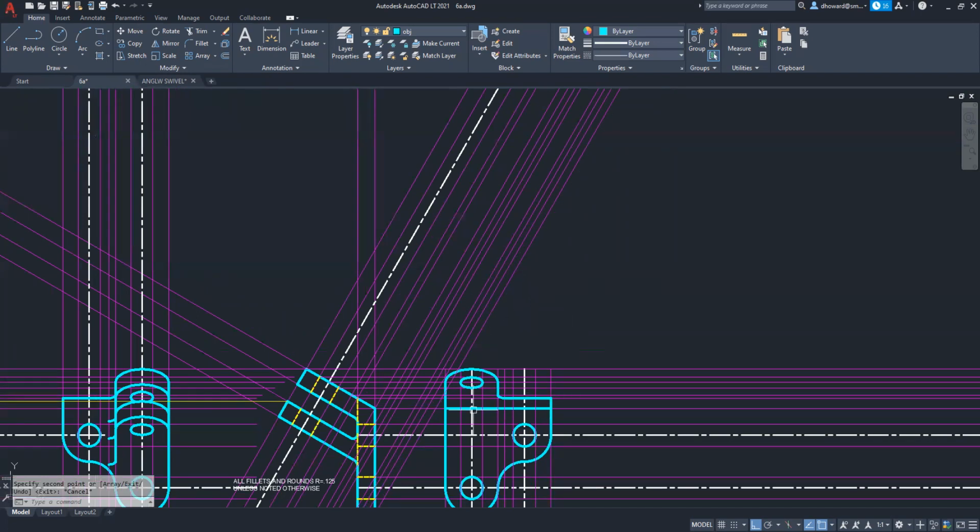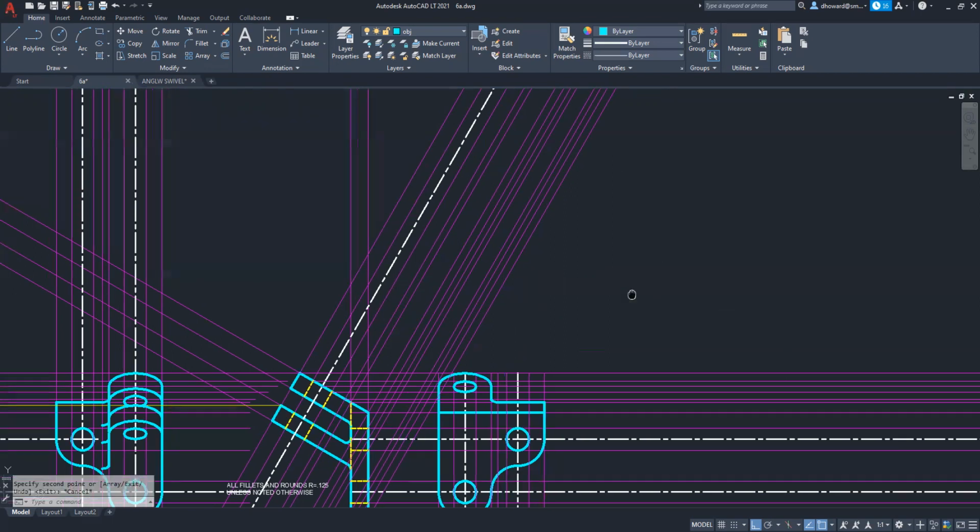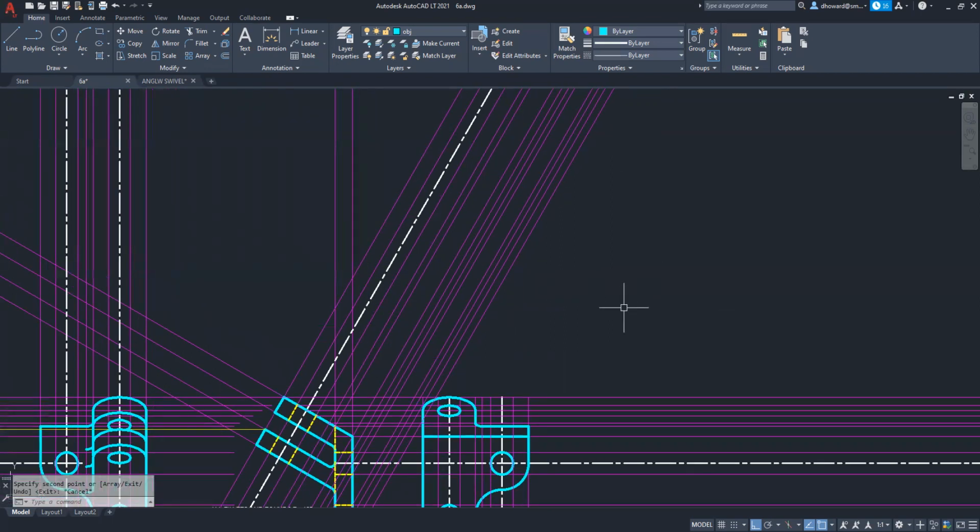Rather than bouncing these vertical lines and using a transfer line to angle them into this, which I did last time, a bisecting angle to hit this face, I'm just going to redo the offsets again. Both ways work just fine.